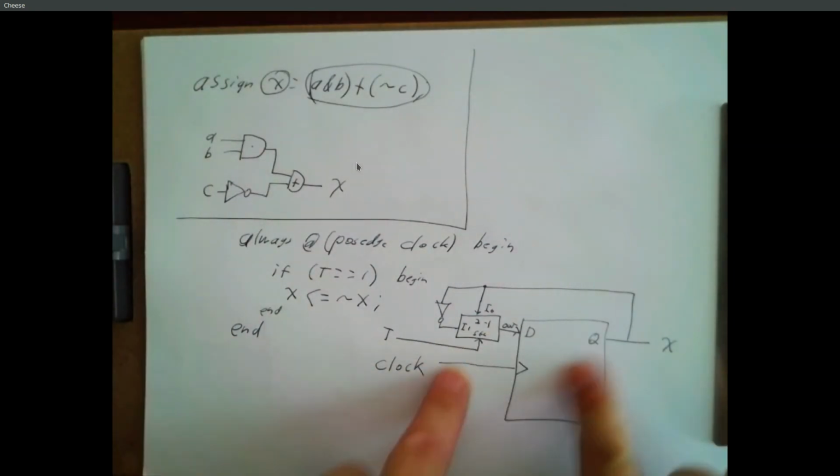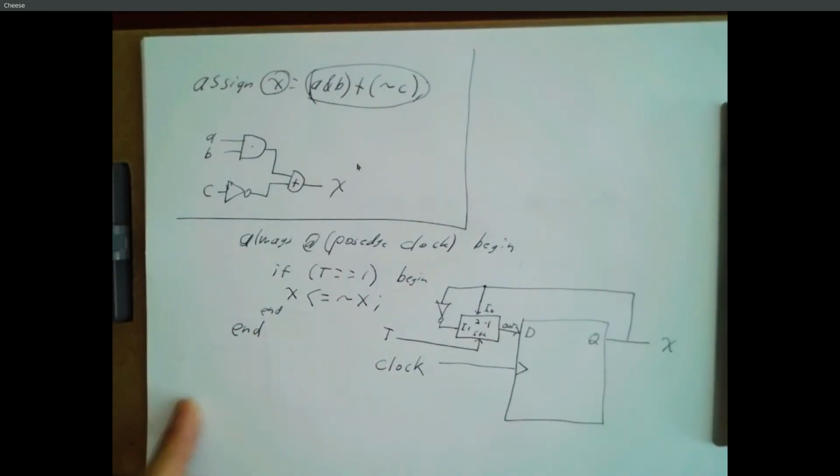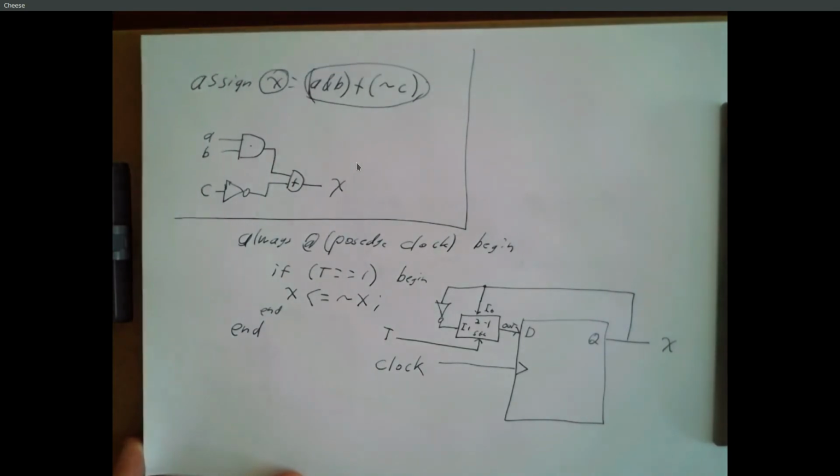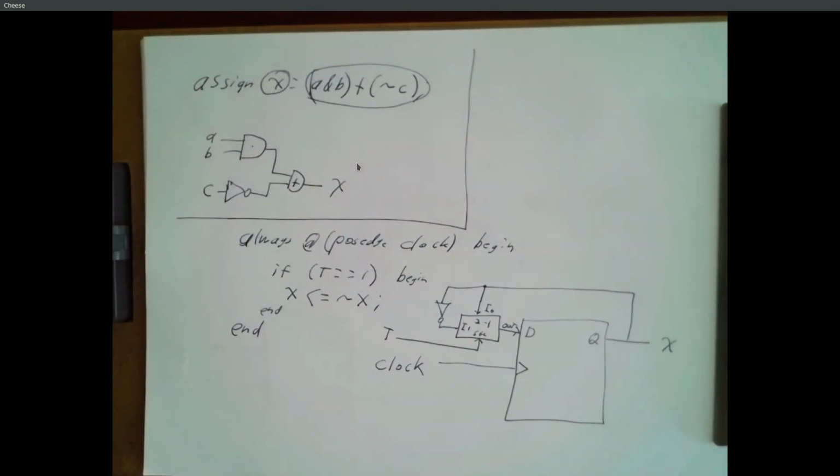So this is something like what would be built from this chunk of Verilog. It may look kind of random or goofy, but it's a model for how a lot of these always blocks can actually get coded. When you write a synthesizer to take Verilog and turn it into hardware, you tell it basically how to do things like this. And it's not as bizarre as it might seem at first. Let me show you what you don't want to do.